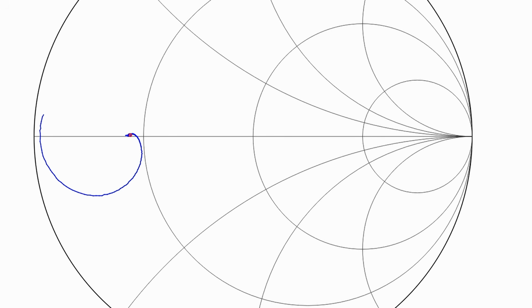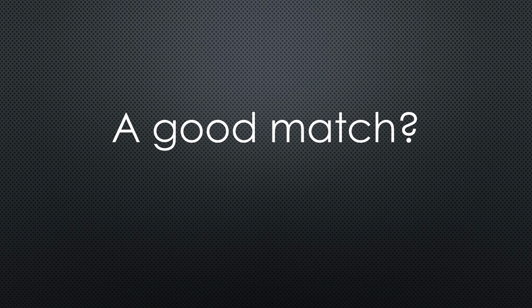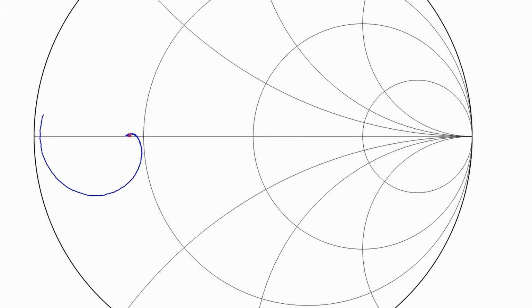Strange, but true. Now we can try to answer the question: would this be a good match if it were an antenna? Ask the shooters how many points they would get if they hit at those positions. The Smith chart is precisely the same. The distance to the sweet spot shows us the quality of the match. Here we would have the best match at 10 MHz with the closest distance to the 50 ohm sweet spot.